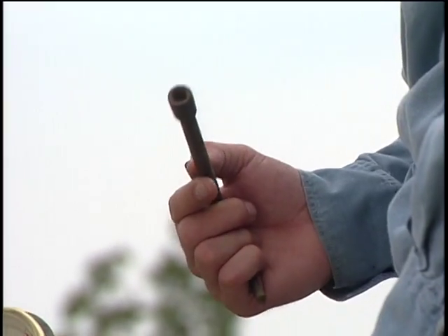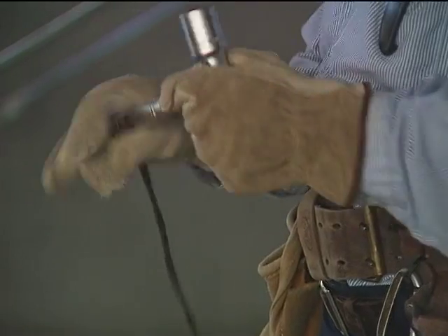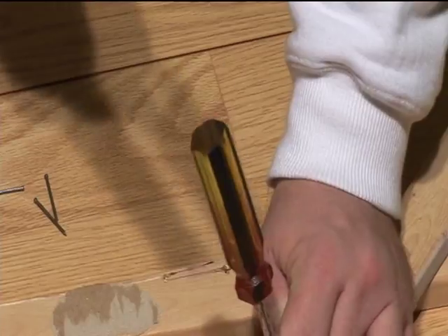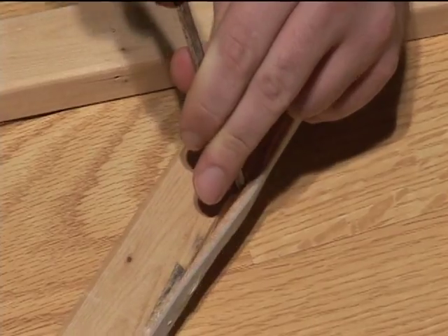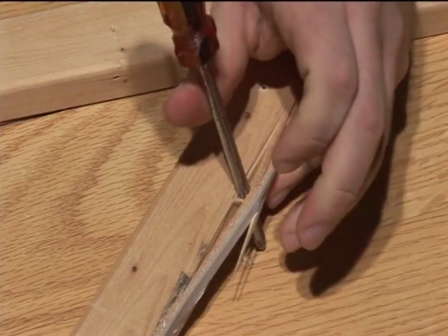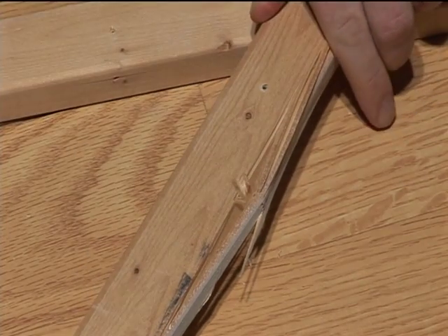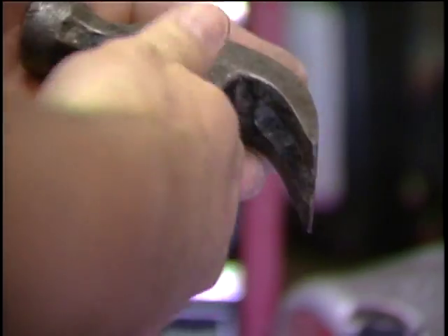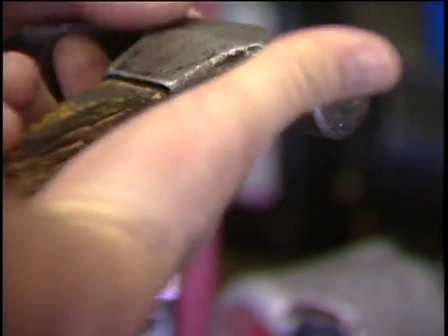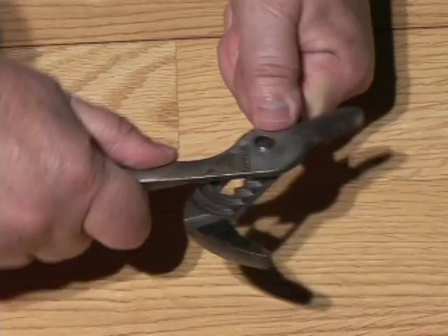The greatest hazards posed by hand tools are a result of misuse and improper maintenance. Never use a screwdriver as a chisel or use a chisel as a screwdriver. In both cases, the tool can easily break and parts fly off, hitting the user or other employees. Never use a hammer or an axe if the handle is loose, splintered, or cracked. The head of the tool could easily fly off and hit someone or something.